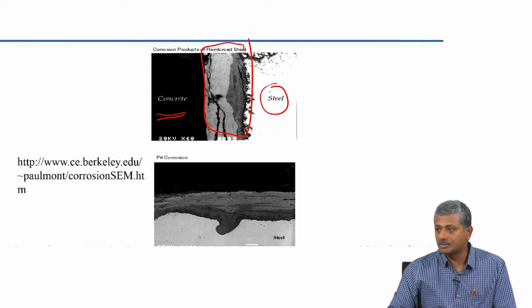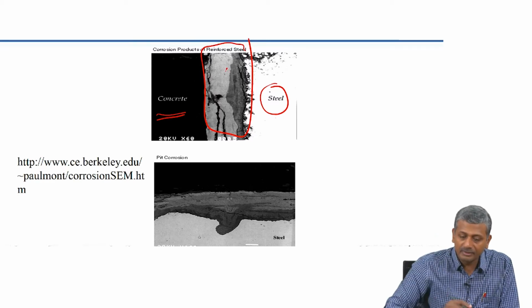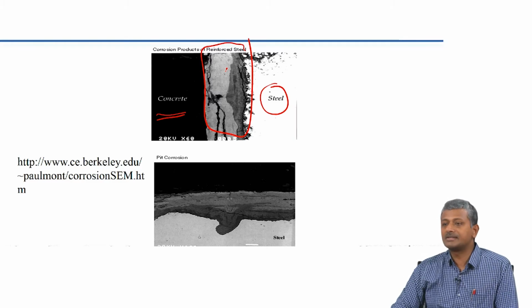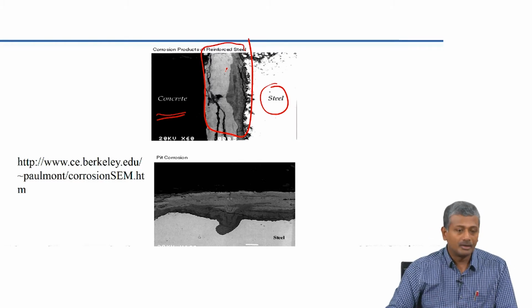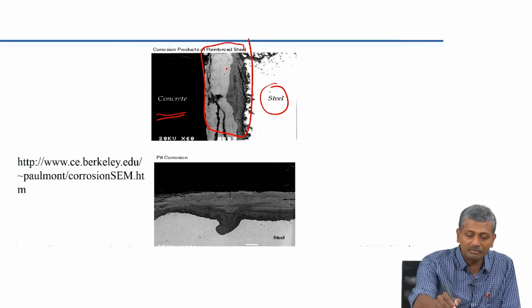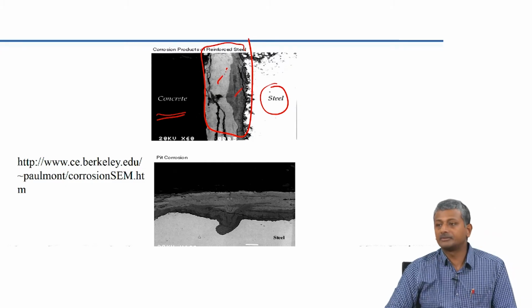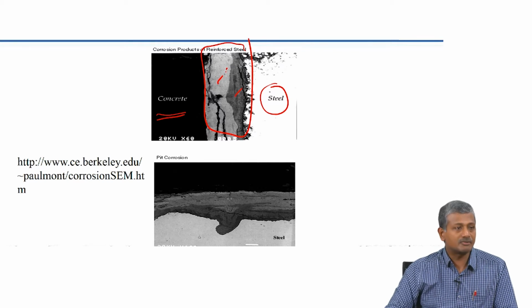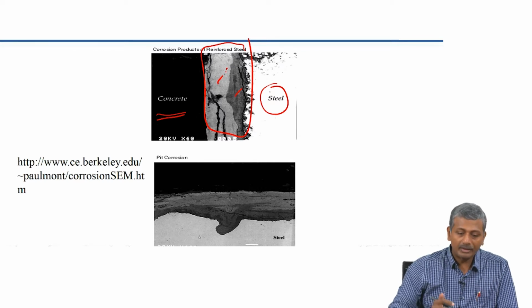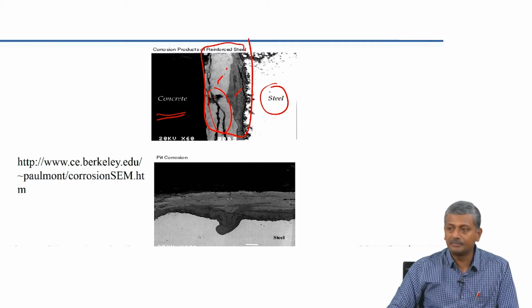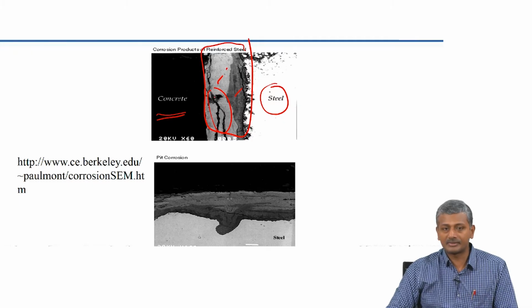made completely white. The intermediate rust products, which have a lesser density than steel, are showing different shades of grey, and you can see here that different forms of rust are forming. There is one darker grey rust and one lighter grey rust. So, different densities of rust are actually forming in the system, and there is a lot of cracking, which indicates that there are some volumetric changes happening in the system.